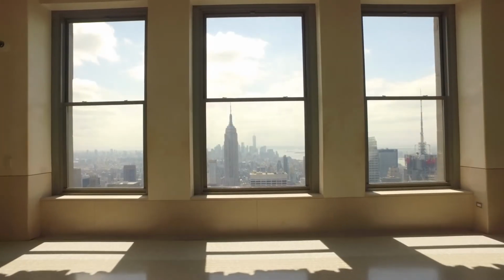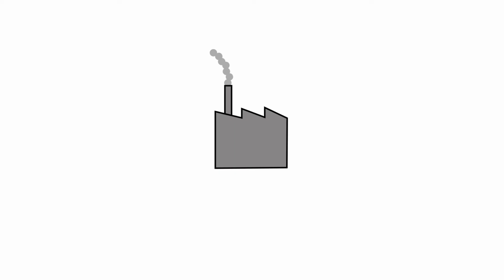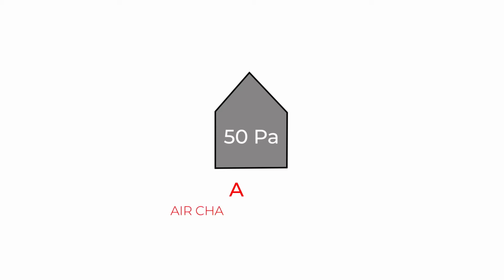Typically, air tightness flow rates are normalized to a dimension specific to the building. In the case of commercial buildings, the flow rate at 75 pascals will be normalized to the skin surface area in liters per second per meter squared of air barrier of the system. Whereas, in smaller residential buildings, the leakage rate at 50 pascals is normalized into the conditioned volume and is measured in air changes per hour, and it represents the amount of air in a space that is fully replaced by air leakage in 1 hour.